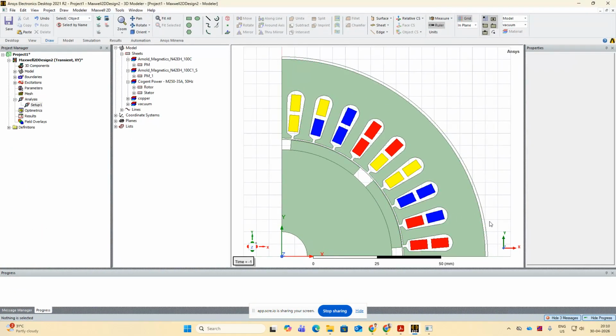First, one thing to notice: for optimization, if I want to change the rotor mmf, I have to change the dimensions, that is the geometric dimensions of the permanent magnet in the rotor. Now, if I want to change the stator mmf, I have to change the ampere turns. So the current per turn in the stator slots and the number of turns in the slots.